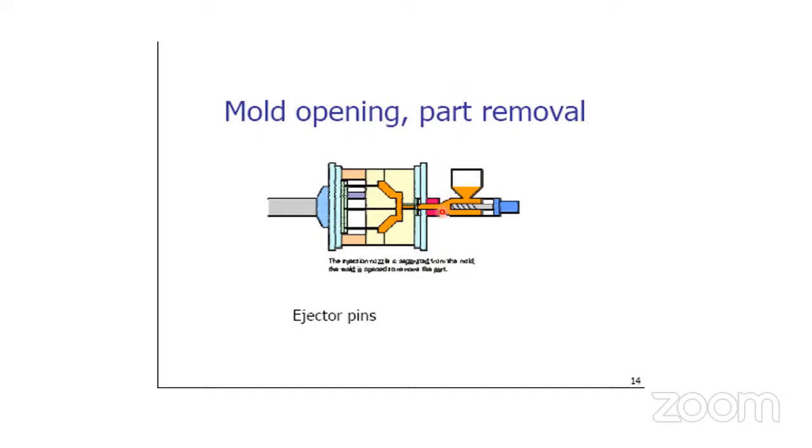Then the screw moves in the backward direction. It prepares the shot. See now, here the orange is visible. It prepares the next shot now. See here, when the article is completely formed, at that time the screw goes backward. Your gate is frozen here. The material is here now. That is called the injection stroke, for the next cycle, for the next shot.